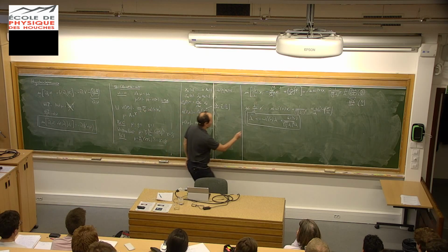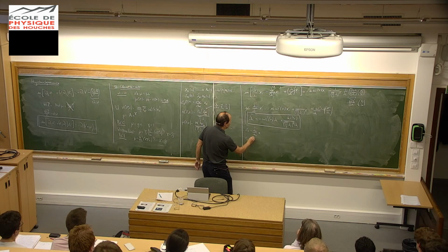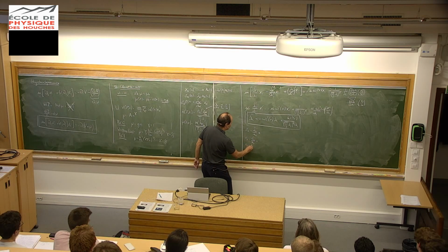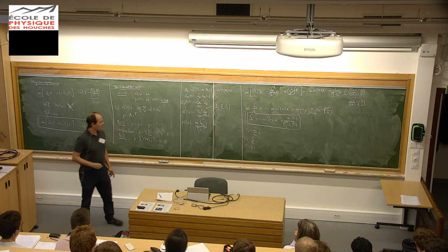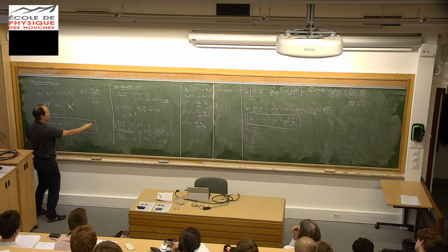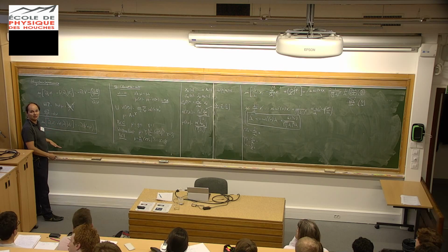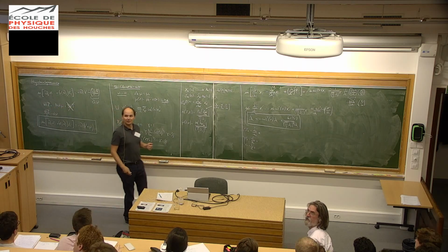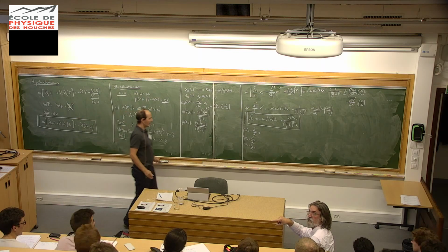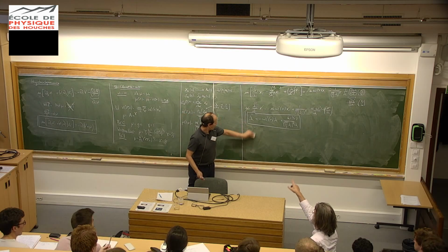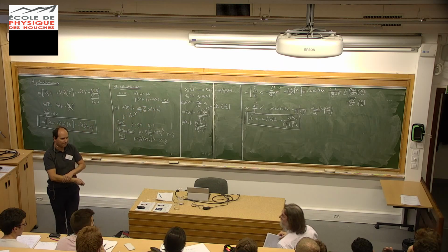So the explicit expression will be V_x is equal to lambda_x dot divided by lambda_x times x. V_y is equal to lambda_y dot divided by lambda_y times y. V_z is equal to lambda_z dot divided by lambda_z times z. No, because I differentiate. Here I have 3 equations, one for direction x, one for direction y, one for direction z. And so I look at all 3 equations independently. And so when I differentiate with respect to time, in fact, we come back to the x, y, z, which are independent variables with respect to t. Although we used the expansion lambda t to develop the space, then we come back in the real space.